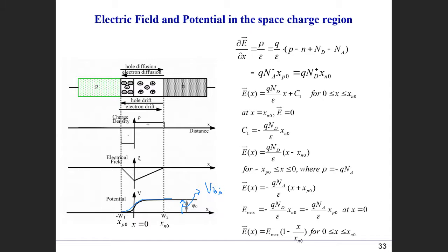Of course, in here, one thing you have to pay attention to is this charge distribution within the depletion region. In here, we apply the charge distribution, saying that within the depletion region, you will have this constant charge, and then abruptly change, and a constant charge across this PN junction. Okay, this is what we call the step junction, describing this step-like charge distribution. So based on this assumption, we obtain the electric field and potential.